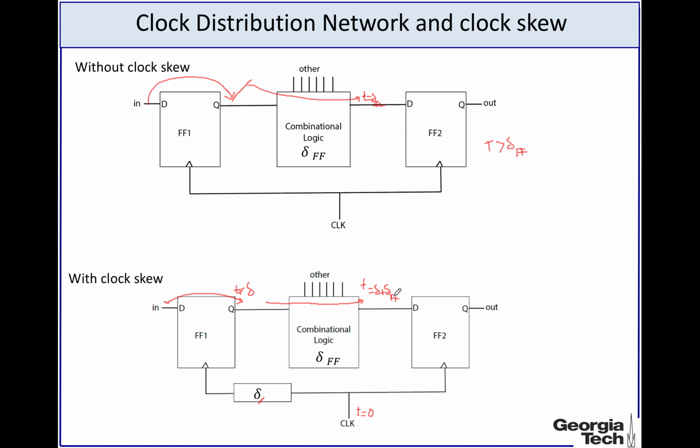In the next clock cycle, the output of the flip-flop will go into the final output, and based on this, the clock period has to be larger than delta plus delta ff.